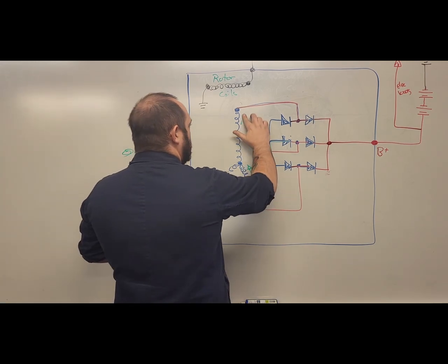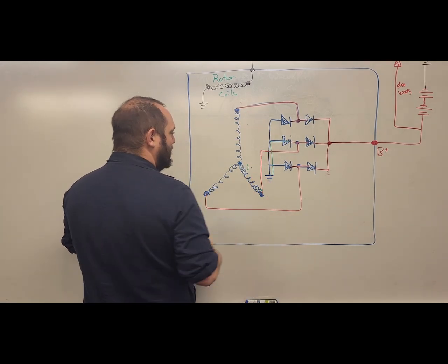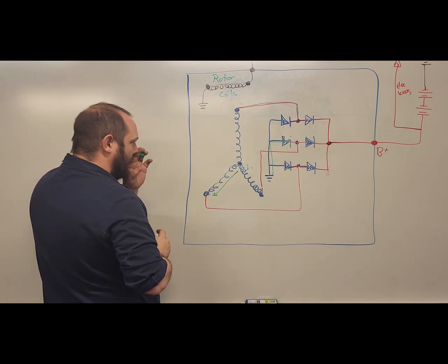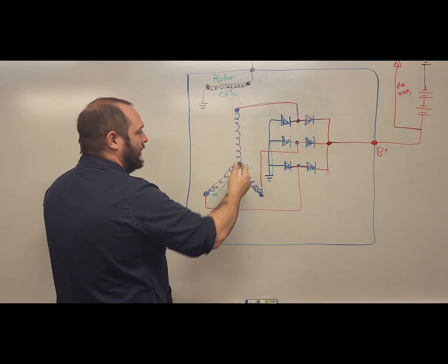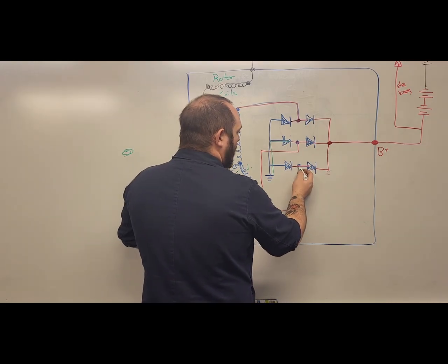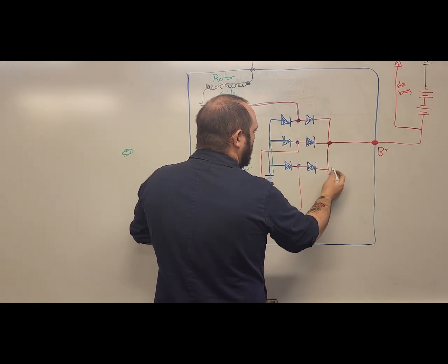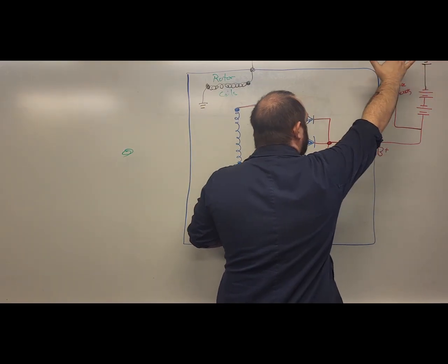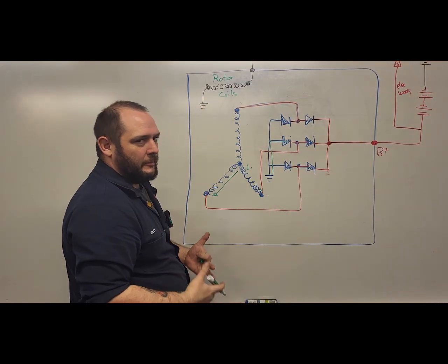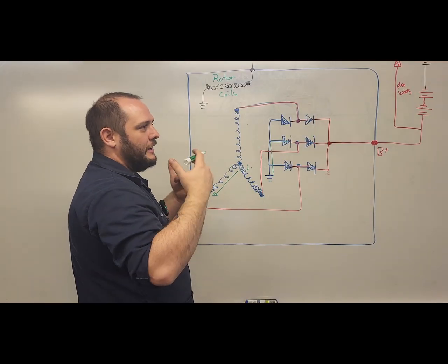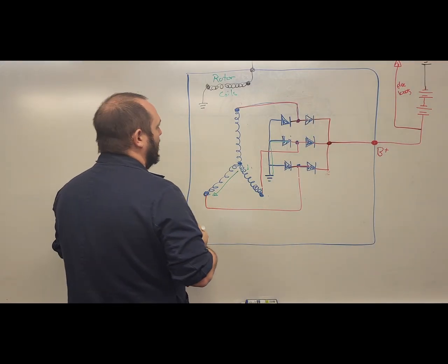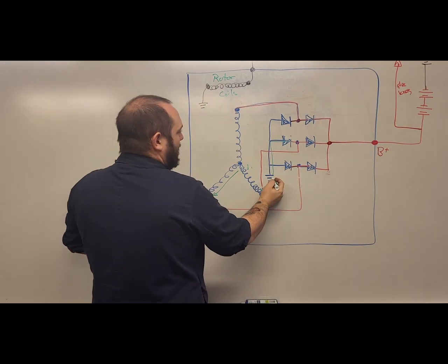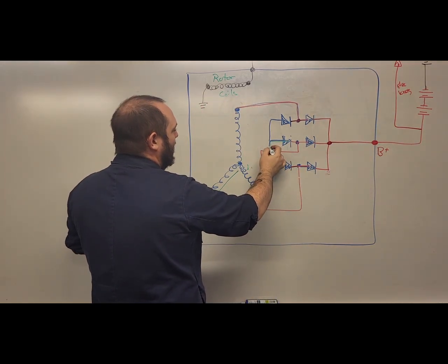If I was to choose 2 different legs, let's say we're going to induce a current and go out on this leg. It doesn't really matter to me which leg we go out on, and we can return on either leg. So we'll go out, this diode will shut off, it's a positive flow, so it will flow through. These 2 diodes won't allow that flow through. It will go out to my electrical loads, charge my batteries, run any lights, run any electrical loads, whatever those look like in your given instance, and then go back to ground, at which point it will flow back. And I don't care which leg it flows back on.